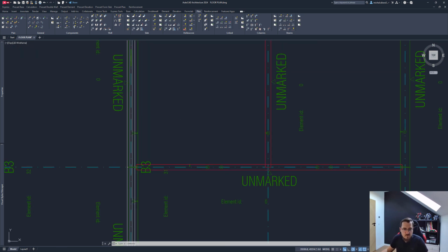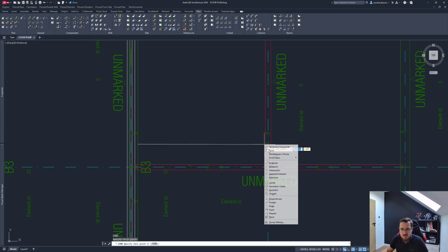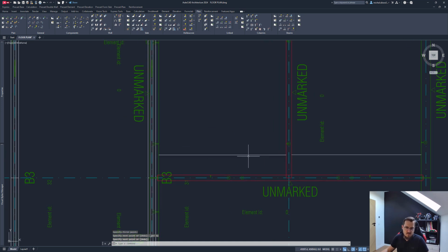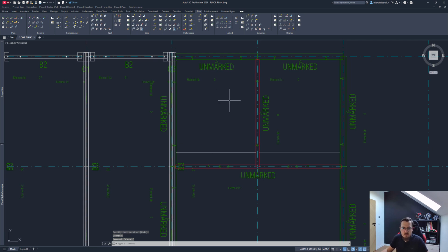One thing of note, I'm just going to create auxiliary lines for me, very quick, just so it's easy. Same thing here, and perpendicular like that. Why? That's because I just want to divide those walls exactly in the middle of the span here for my convenience. But other than that, there's basically no other particular reason for me to do that. Right. So let's split up those walls.